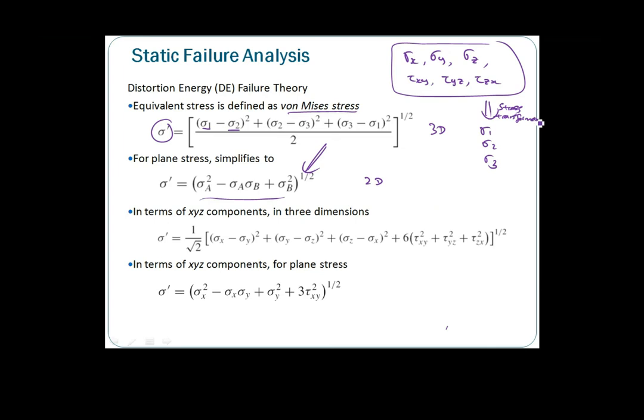That is where your Mohr's circle comes in. Our sigma 1 is our maximum principal stress, or maximum normal stress, of this set of stress elements. At the same time, we can also get tau max from the Mohr's circle or stress transformation. We have sigma 1, sigma 2, sigma 3, tau max, and their respective planes. This is what we have learned in mechanics of materials.